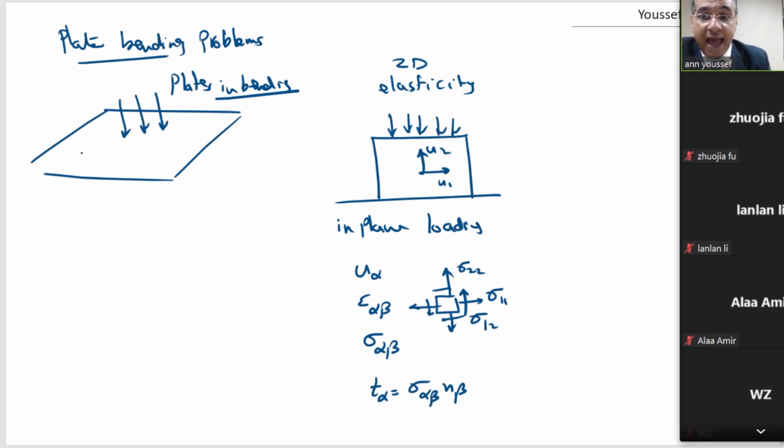So here, actually, we will start to have one vertical deflection. So we have here, for example, x1 and x2. And now we have here x1, and this is x2, and this is x3. Okay? Still, we have a two-dimensional problem. It is not a three-dimensional problem, because our involved Laplacian is the two-dimensional Laplacian. So here we have U3, which is deflection.